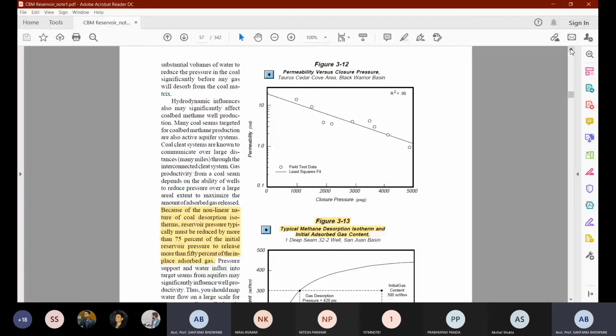So if you are going to take out the water, what will happen? The moment you take out the water, you know the pore volume, you know the effective stress principle. Effective stress is the normal stress minus the pore pressure, or the water pressure, which has to be reduced. The pore pressure has to be reduced for the effective stress principle from the normal stress component only, but not from the shear stress component.